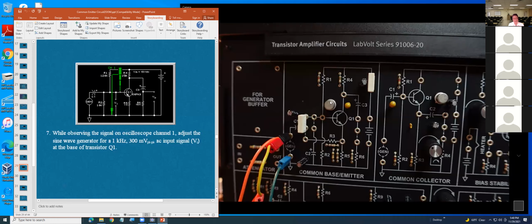Right. Normally at the beginning, they ask for the power supply to be 15 volts. So basically you connect the DMM high here, DMM low here, right? If it's not 15 volts, you have to adjust the positive voltage to make sure you get 15 volts. That's in the procedure; when you do it, they tell you how. Only thing is, if you get any question regarding the DC measurement, then I can tell you.